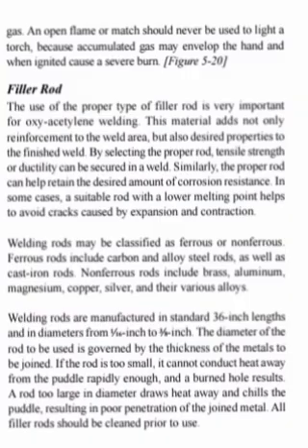By selecting the proper rod, tensile strength or ductility can be secured in a weld. Similarly, the proper rod can help retain the desired amount of corrosion resistance. In some cases, a suitable rod with a lower melting point helps to avoid cracks caused by expansion and contraction.